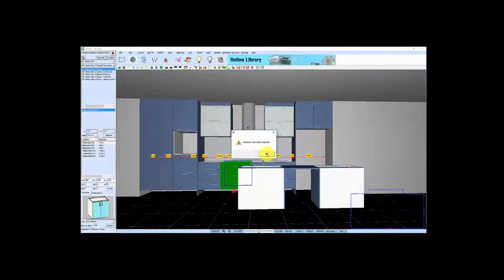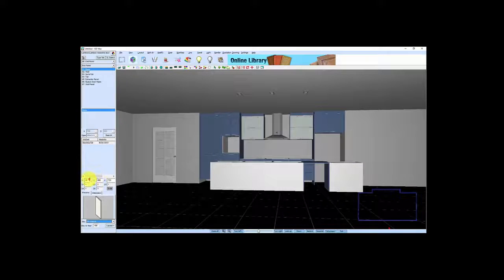So what I want to do now is place a bar back on that cabinet. So we go to base units, end panel, decorative panel, go OK. The width is 1600, is 1921. The depth is 16 and the height is 870. I want to put that on the floor. Let me just press layout.